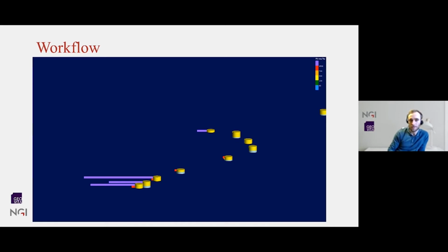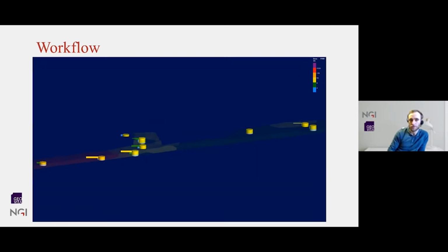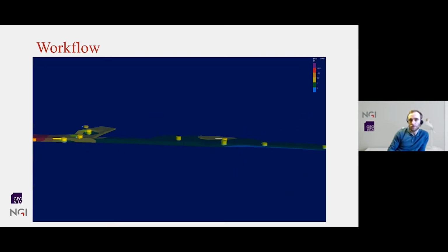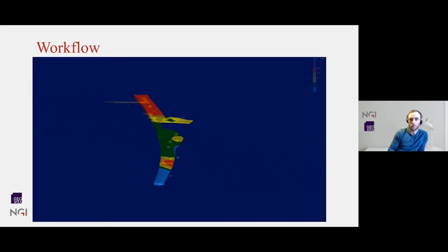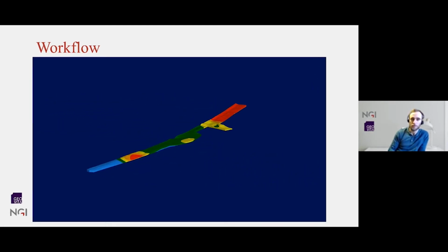Here I'm looking at lead, and also compared to other parameters, here it's the polyaromatic hydrocarbons. In total, you can use these borehole data to interpolate between the boreholes and create a 3D model of your contaminant distribution.